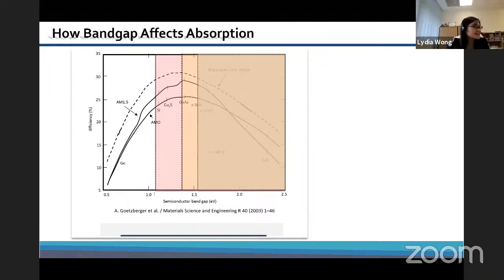Okay, so you want to change your answer? Actually, you cannot change anymore, but the majority of you guessed correctly. Twelve of you guessed the correct sequence based on the band gap: silicon, gallium arsenide, then amorphous silicon. However, in reality, gallium arsenide has the highest efficiency compared to these three. Amazing, right? The gallium arsenide band gap is actually larger than silicon. Why does it have higher efficiency than silicon?